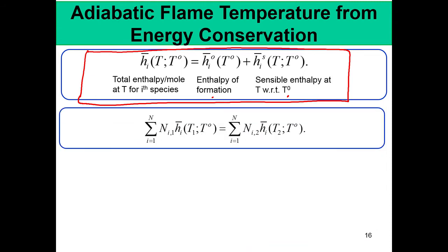Now, suppose you have combustion happening at constant pressure inside a vessel, and the vessel walls can be sealed. So, there is no heat crossing the control volume or system boundaries. So, essentially it is energy from the chemical bonds becoming sensible enthalpy or vice versa. There is no external energy coming from anywhere, you must remember this. So, it is essentially a rearrangement of the enthalpy between the enthalpy of formation and the sensible enthalpy that is happening in combustion.